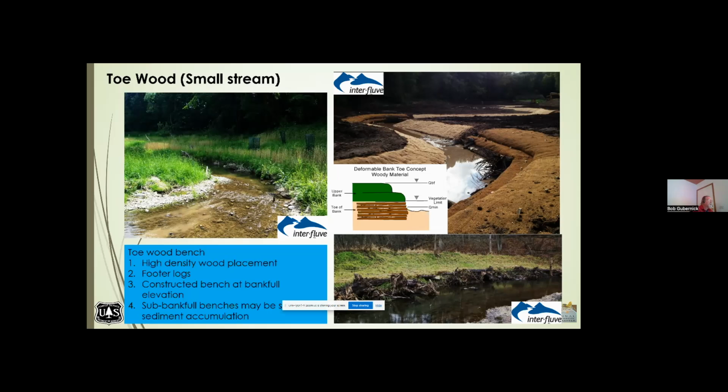If you don't get the vegetation established on your soil wrap coir fabric blankets, then your structure is going to go away in time. This whole structure, like I said, relies on that vegetation colonization, whereas with a lot of the other log jam type structures, it doesn't.